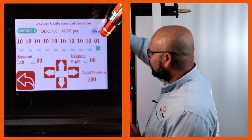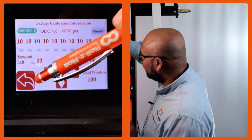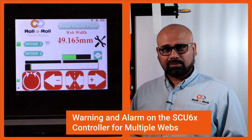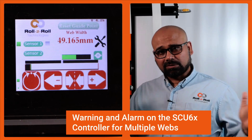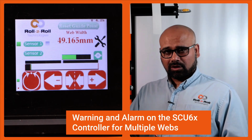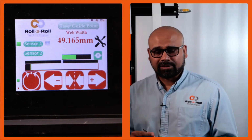This is a factory calibration number that you need to enter. The slope correction is another number you need to enter in this screen. When we do multiple split width measurement and we have a digital output that triggers an alarm limit or a warning limit, you can tie that to a stack light. If you have multiple web widths, multiple split widths, and any one of them is out of range, then that stack light would get triggered. We have one output for alarm, one for warning, and one for all good. If any one of those lanes violates that condition, that digital output gets triggered.